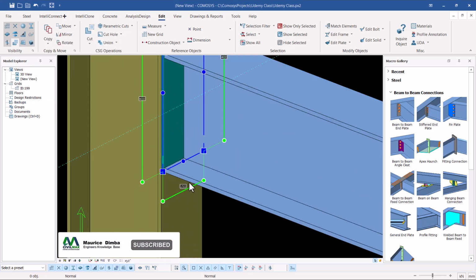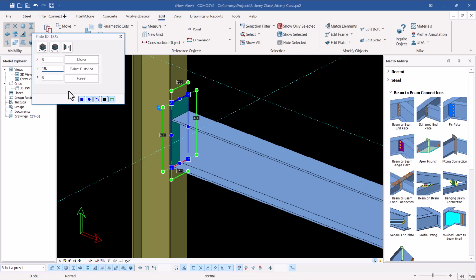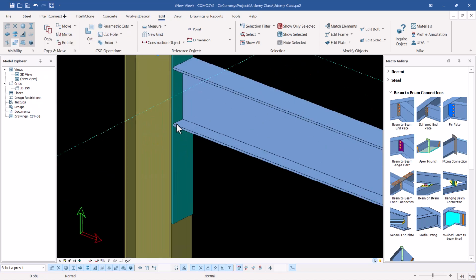So I can do the same thing downward here by clicking on that handle. If I come here, I can click move, but this time I want to move in the negative direction along the y-axis. So I'll have to prefix this dimension by a negative sign. But because a haunch might be applied here, I need this to move slightly more, to 400 or 500. I can give it 500 right there, then prefix that dimension by a negative sign. So I'll go ahead and click move. If I click move, I'll have that in place. So you can see we have that.